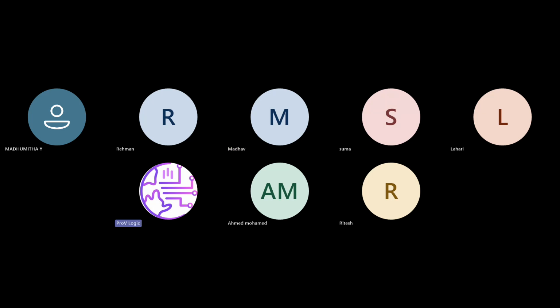Okay, no problem. What about Suma? Did you try with the other version? Yes, with 17 I got. You got it, okay. So remaining all, try to install the 17th version for ModelSim. Quartus Prime anyway will work with the new updated version, but for ModelSim we are facing some errors. So for ModelSim, you can install version 17.